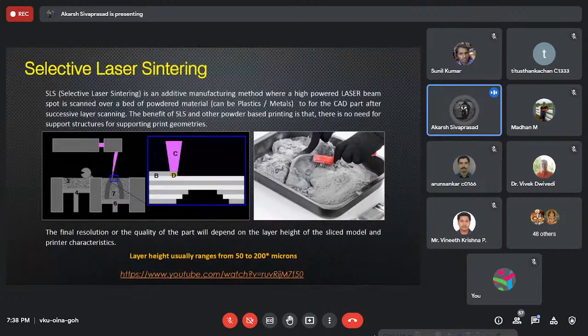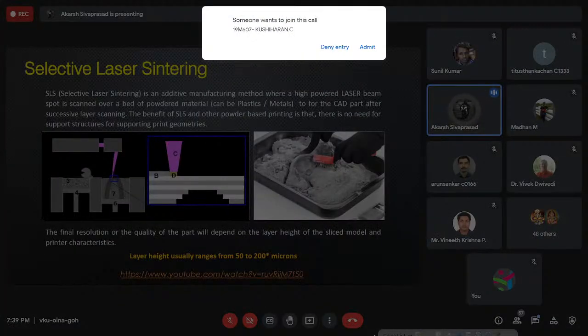and it's a little time consuming because you have to make sure that the powder that you deposit on the previous layer is exactly precise in terms of thickness that you want to cure, and also since the scanning optics, it's going to take a lot of time to cure the layer. It's not a one flash operation. So if you print one small part in the middle, it's extremely fast. But if you have a really wide part, which is extremely thin, it's going to take, call it, like 10 times the time to do that.